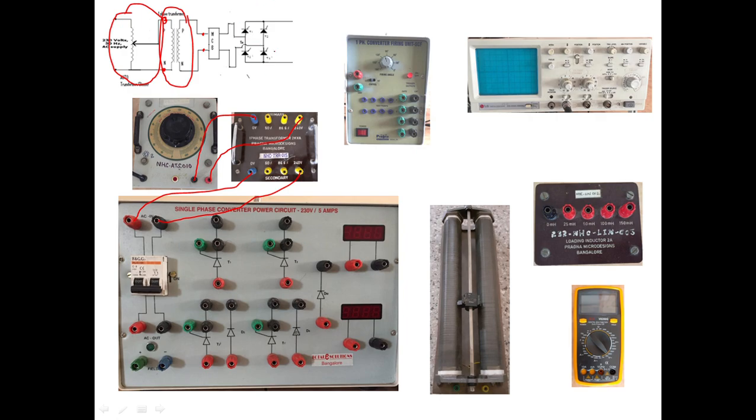That is this connection here. You can see four thyristors, SCRs, connected in this way. Now I will take T1, T2, T1 dash, T2 dash. Now how are these connected? You can see that this anode is connected to T1 cathode. So we need to connect a wire from here to here, and again there is one more connection from anode to cathode. So from this point I'll connect one more wire here. And these two are connected, and these two are connected. Done. We have done this connection now.